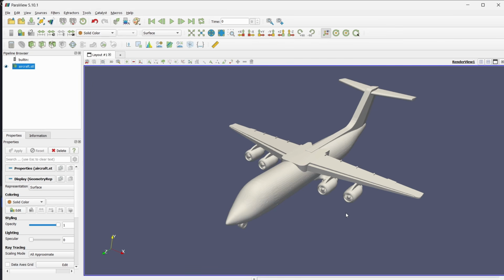Okay, so this file which I have downloaded is in .stl format, but there is a problem in that. .stl comes in two versions. One is ASCII, the other is binary. Generally, when you download a model from any CAD modeling software as STL format, it will be mostly in binary format and not ASCII, because 3D printers can work well with binary STL files, but in case of CFD, especially OpenFOAM, you need ASCII format STL files.